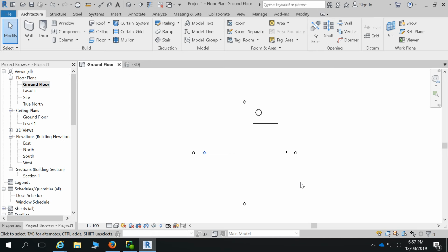Okay, so depending on what we're trying to get rid of on our screen, it might work one way and not the other. So if you had a model and you wanted to delete 2 windows, you wouldn't select the whole model and then try to filter it out because you might have 10 windows in your model. So that's not going to work. That would be more like select one window, hold your control down to add plus, and select the second window and delete those 2. Okay, so there's lots of different ways you'll find work better for certain things.